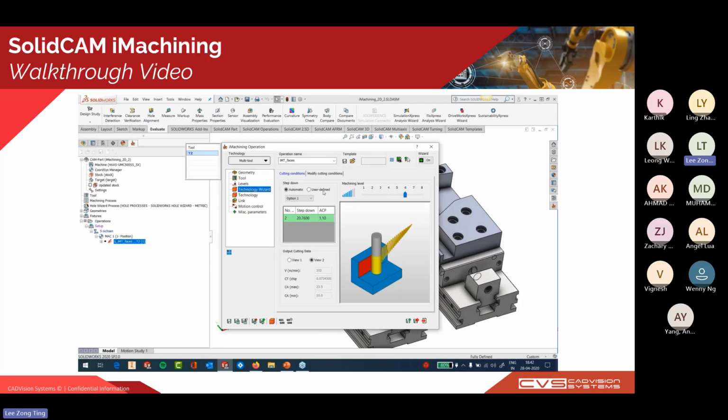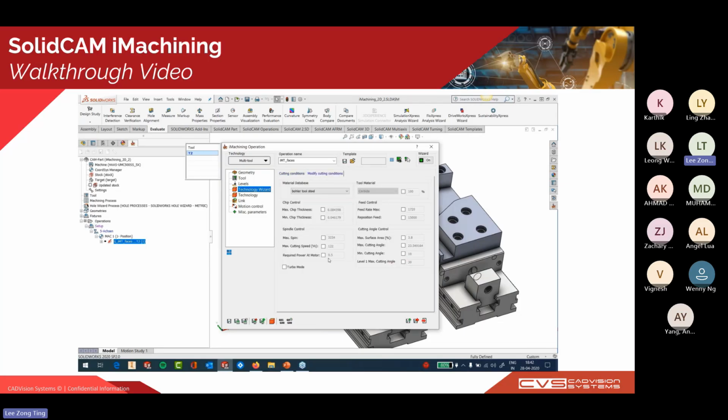So we don't need a lot of CNC knowledge to guess or to get those parameters. We can use iMachining and it will be easy for you to get on board and get a first time cut success. You can see that I can use a turbo mode to increase my spindle power. Now I'm operating the motor at 7.5 kilowatt.